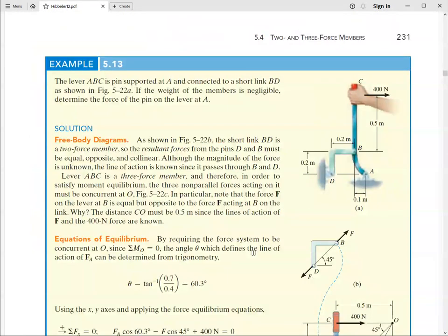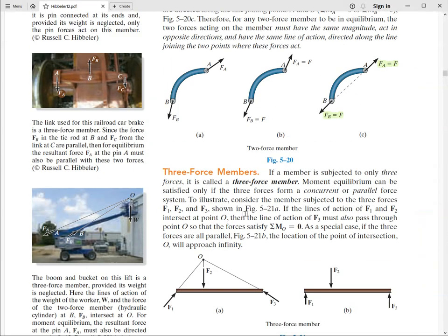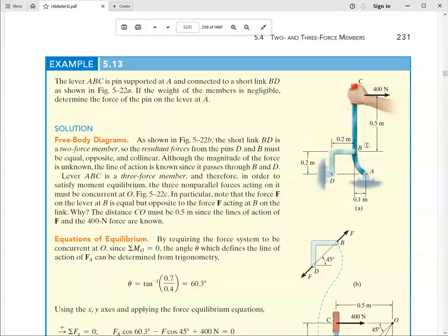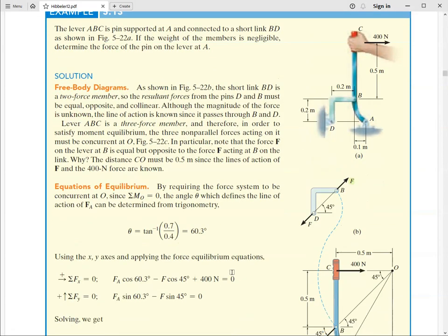Right. So yeah, recognize a two force member. Its shape is not relevant. It could be a straight link or a shaped link, like in this problem, it's L-shaped, but as being a two force member, the forces are collinear. All right.